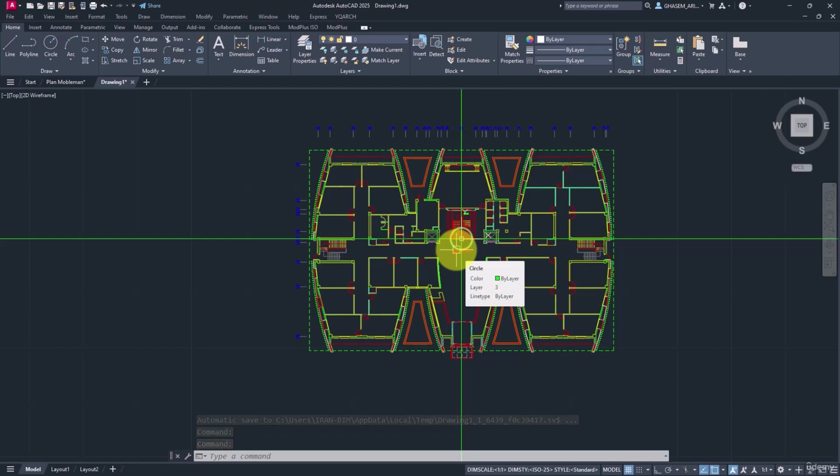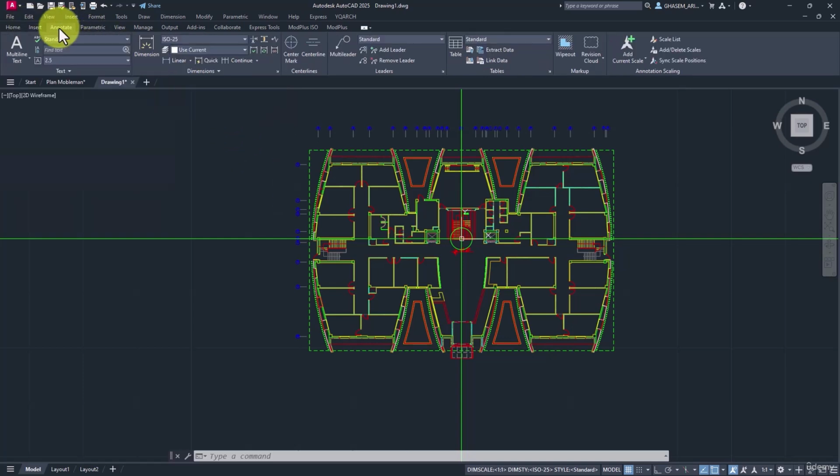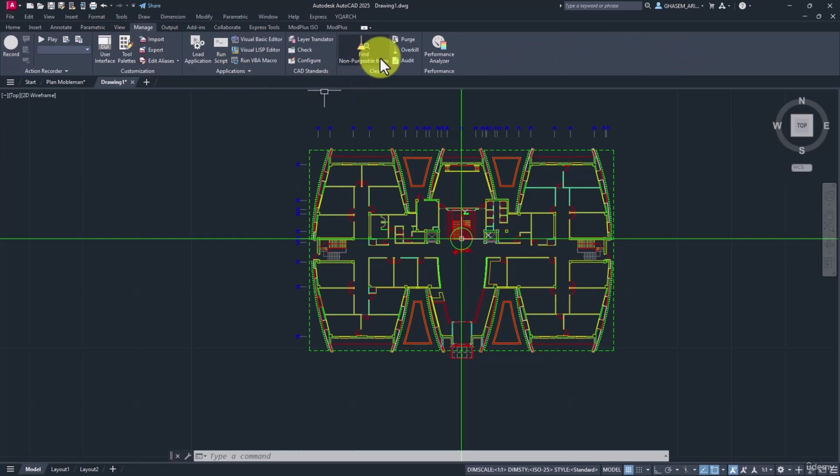So guys, don't forget to check the scale of your drawings in AutoCAD, and after that, as you remember, we deleted some of the redundant objects like the blocks, as you can see that they are not usable there. For instance, we deleted the dimension lines, the dimension styles, the text styles, and so many other elements that must be deleted to optimize the file.